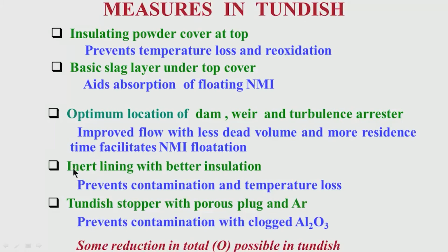Then as I was mentioning, we must have a good insulation, it should not cause contamination or temperature loss, this is very important. Then the tundish stopper with porous plug and argon, this is very important, because this prevents contamination with clogged alumina. So as I was telling you,